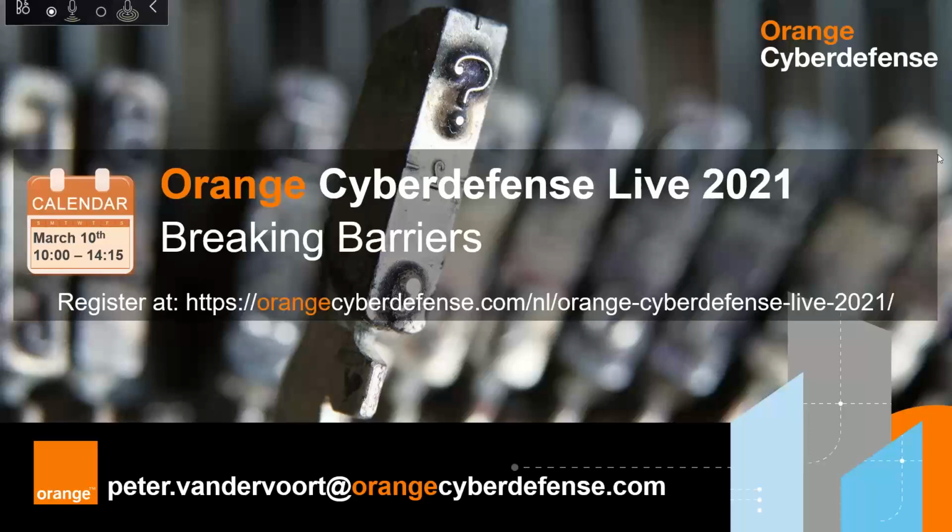So that's why it is important that if you use an IDS system, and I'm really talking about IDS, intrusion detection, and not intrusion prevention, it is imperative that it is a passive solution. So it must just listen on the network, and it must not interact with any OT-related devices. And the vendor can never dictate that you cannot just listen to network traffic, right? So you're just responding to what you see on the network, and you're not interfering with any OT device.